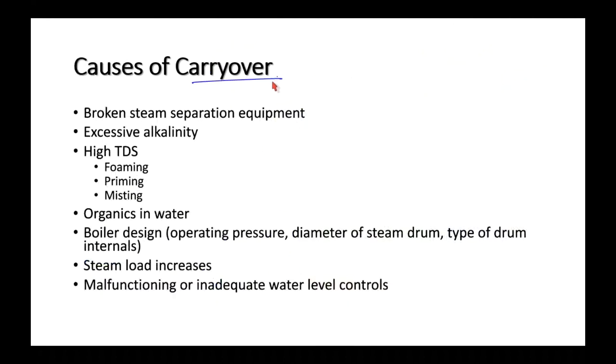So, what causes carryover? Broken steam separation equipment inside your drum. Okay, so you are going to have some sort of baffle, and maybe you've got a cyclone separator, and maybe you've got chevron dryers, and maybe you've got a silica washer. Maybe you've got some wash water going on in there.